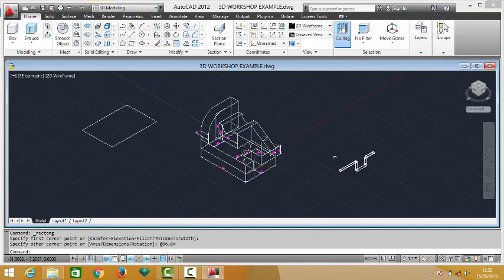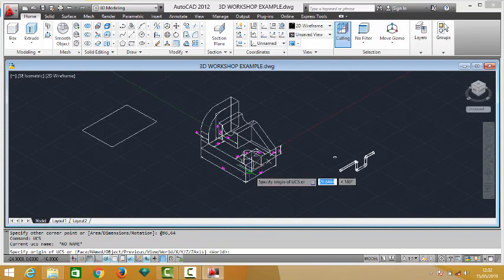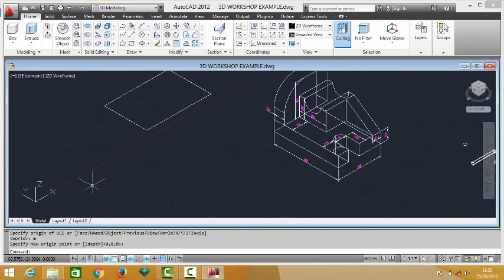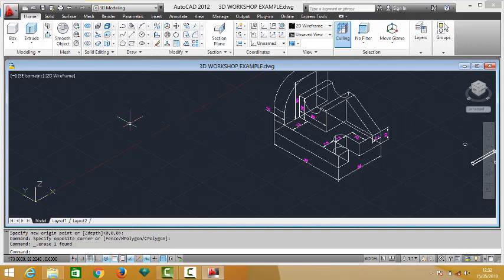Let me take my UCS, enter, M, enter. Okay, this is my UCS. My X is taking 96, my Y is taking 64, while my Z is taking the height. So what I will need to do is type in for the rectangular base to be in this direction, because I want to be in this direction.